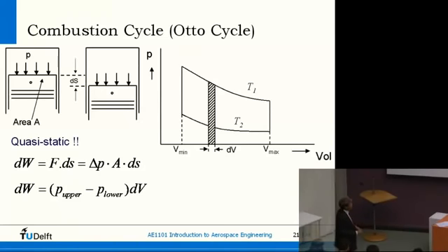So if we then draw this diagram, pressure against volume, this means that if we change the temperature or we change the volume, in this case we have a constant temperature, but we change the volume, the piston is moving, volume gets larger, then the pressure becomes lower. So this is a P times V that's constant because the T is constant. Then this area is basically the amount of work that was being done by the gas here.